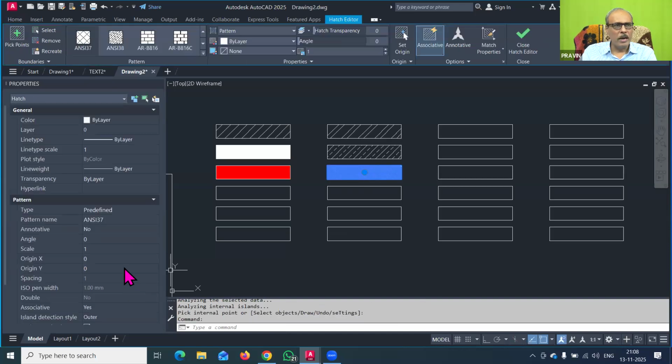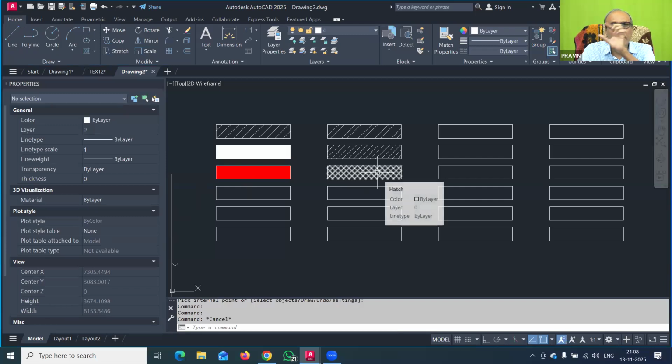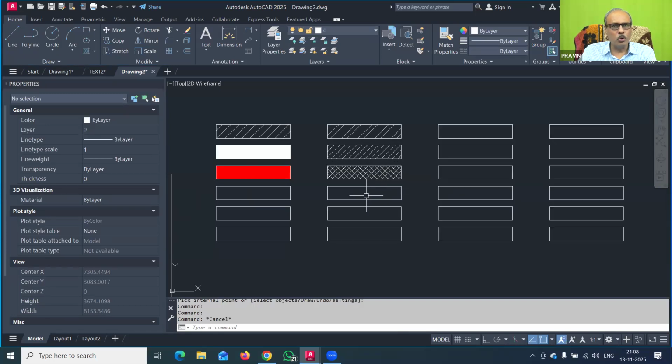So click here and now you have to adjust the scale, so I will place it as 20. So it is showing the grill. Whenever you want to see a simple grill design, you can use this hatch pattern. That is very simple. Now, in the cross section we sometimes require concrete also. So again, that we will see.